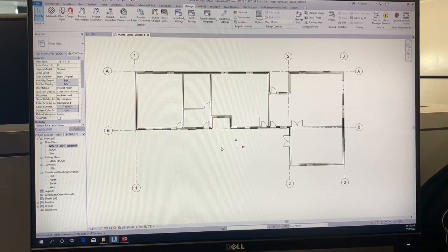Now, just a few things in regards to the as-built drawing that's missing in this file. When you do your as-built drawing, obviously we have our dimensioning. I asked you to dimension the building, so that's something I didn't put in this drawing, but obviously you should have that on your as-built drawing. So let's create our first sheet with this drawing on it. This again is our as-built.